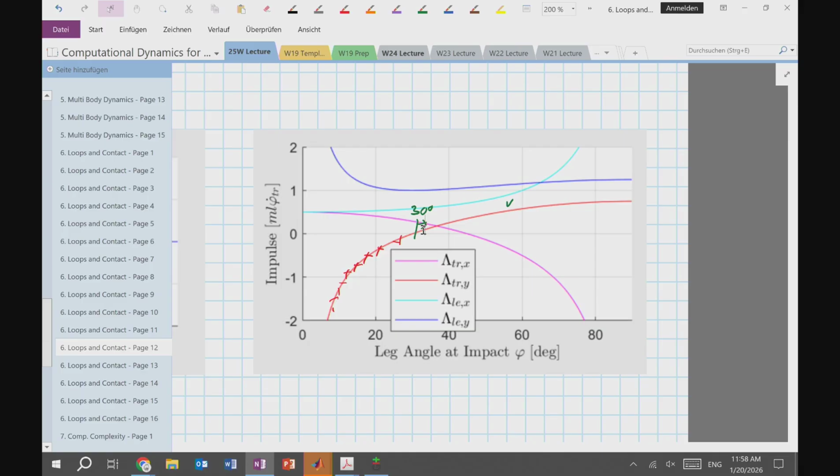Now, with this, solving this problem actually becomes quite simple, because my vertical force, my Fy, is going to be equal to the gravitational force G. Then I set up a balance of moments about this point, which says that this distance times G equals that distance times this force here, which gives me some finite friction force.